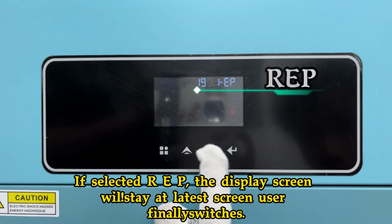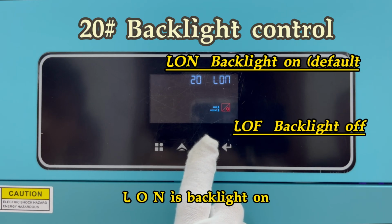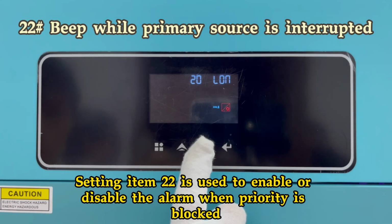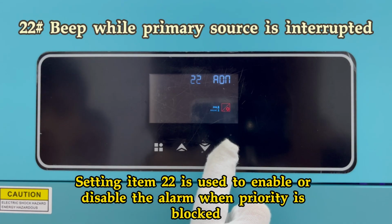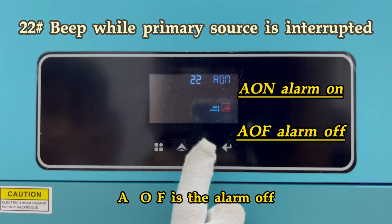If selected REP, the display screen will stay at the latest screen the user finally switches to. Setting item 20 is for the backlight switch of the screen. LON is backlight on, LOF backlight off. Setting item 22 is used to enable or disable the alarm when priority is blocked. OF is the alarm off.